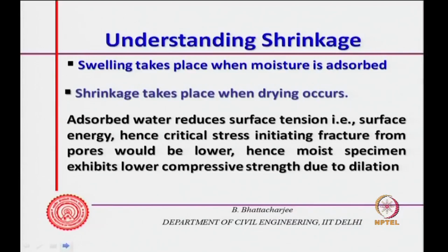So, adsorbed water reduces surface tension, surface energy, hence the critical stress initiating fracture from the pores will also be lower. Since the surface energy becomes low, if you recollect when we were talking of strength, critical stress is a function of the square root of E gamma divided by pi into half of the crack width, or pi r.